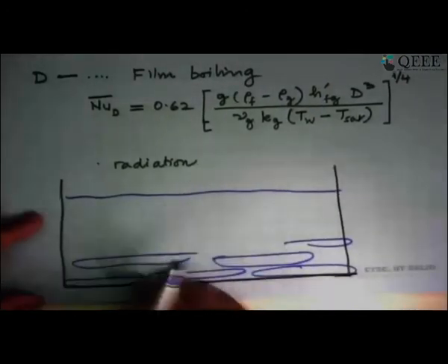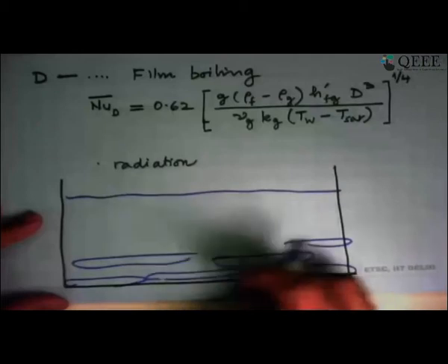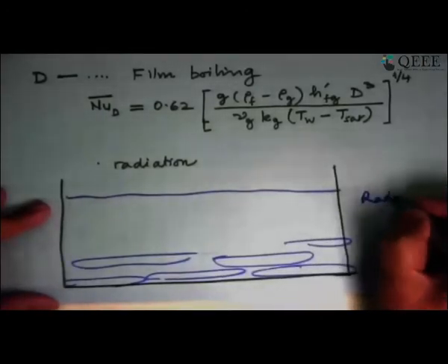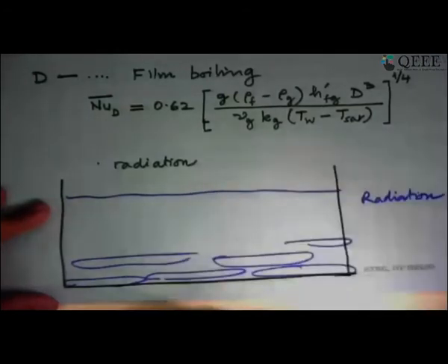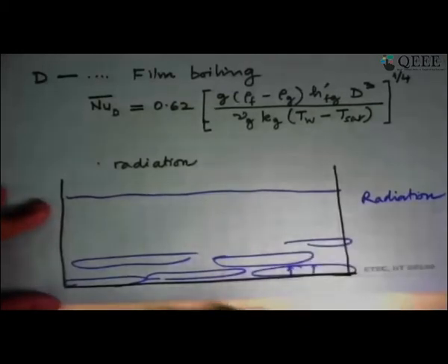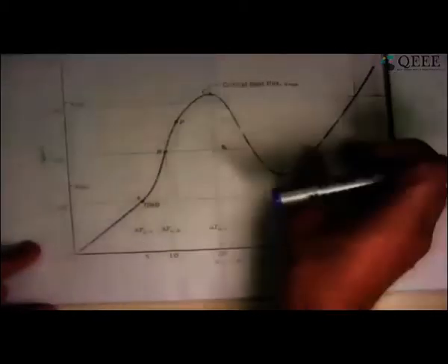This is why it is low, but then as temperature goes up, the other mechanisms of heat transfer come into play. The rate at which the film breaks slightly increases, so that gives a slight advantage, but a little while later radiation starts to come in. That means from this surface radiation now happens to the liquid surface, and this is happening because of differences in temperature. If you see the end part of this, we're looking at a temperature difference of 1000 degrees Celsius, 800 degrees Celsius. Very large temperature differences. There's radiation taking place, and that is what is causing this increase.